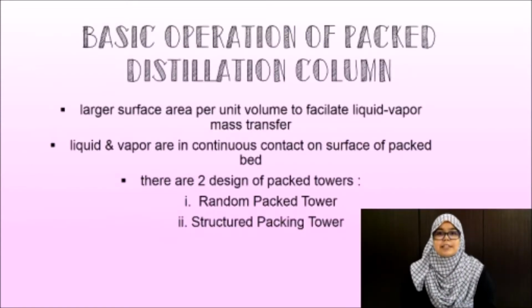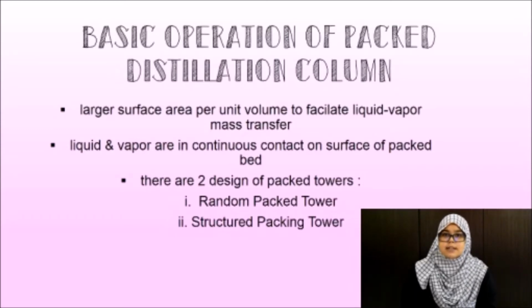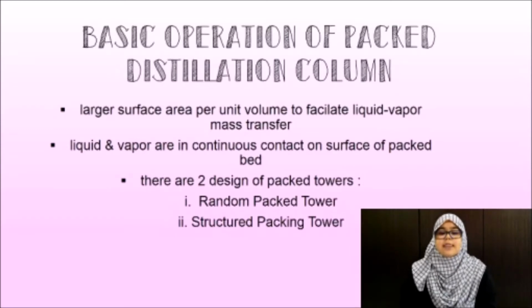The basic operation of a packed distillation column is that it has a larger surface area per unit volume to facilitate liquid vapor mass transfer. Liquid and vapor are in continuous contact on the surface of the packed bed. So, there are two types of design of packed towers, which are random packed tower and structured packing tower.